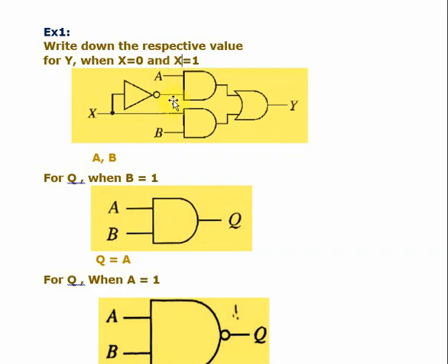I have assigned 1 here. Then you see 1 and 1, you will get 1 here, right? Then you compare this output with A. Equal, no? Here also 1, here also we gave 1. So that means the output depends on A in this situation, right? For example, let's say A is equal to 0. Now here you got 1. AND gate, 1 and 0, the output is 0. Then again we can compare the output, here also 0, here also 0. Then finally we can make sure the output always depends on A here, right?